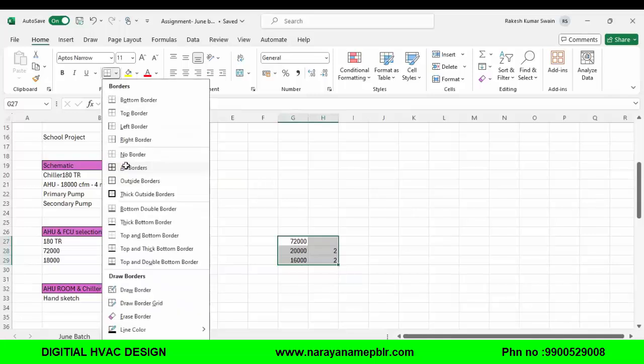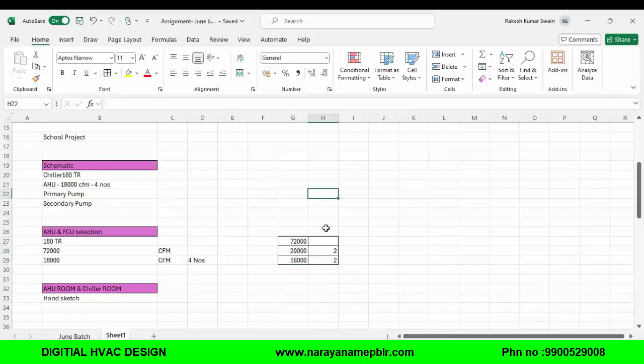But for this selection, I don't think we have learned how to read the catalog. The catalog can be customized. You don't have a standard catalog for this, but if you Google it, you will get some standard catalog. For example, you choose 20,000 CFM and they don't have it, so the next they have is 22,000. If you give 20,000 also, they will supply you 22,000 CFM.